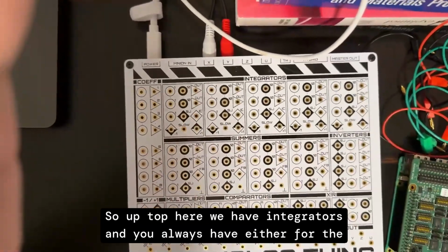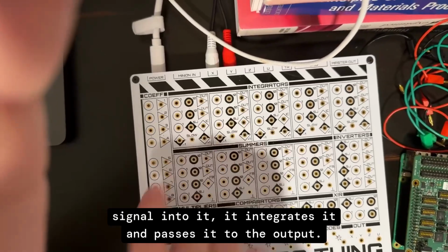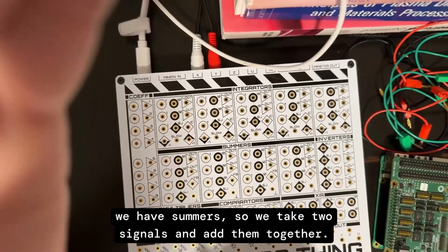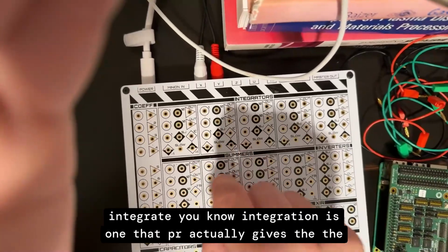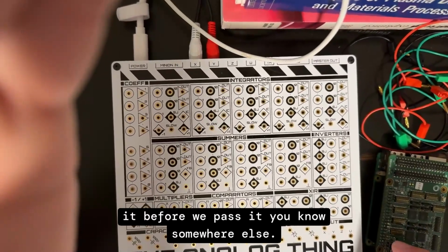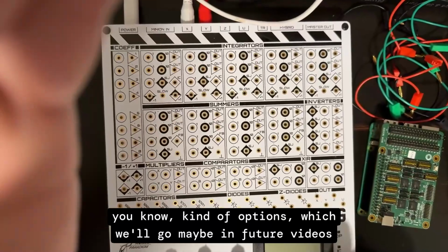Up top here, we have integrators, and for the integrators you have an input and an output. You pass the signal into it, it integrates it and passes it to the output. And then you also have the initial condition that you're going to initialize that integration with. We have summers, so we take 2 signals and add them together. We have an inverter, which gives the negative of the signal, since we might need to invert it before we pass it somewhere else. And then we have 2 multipliers, so multiplying 2 signals, and we have comparators and a few other options, which we may talk about in future videos.